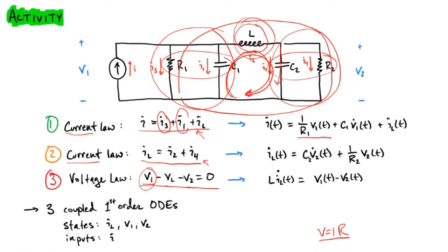We know how to express the current across this first capacitor by using the capacitance times the derivative of the voltage across it. And then IL is something we could substitute for, but because the expression for the inductor looks like VL equals L times IL dot, the derivative of IL, it's more difficult to use this as a state. Instead, we're interested in keeping it as a derivative and then thinking about that element that has the derivative on it as the state. So in this case, we're going to keep IL there.